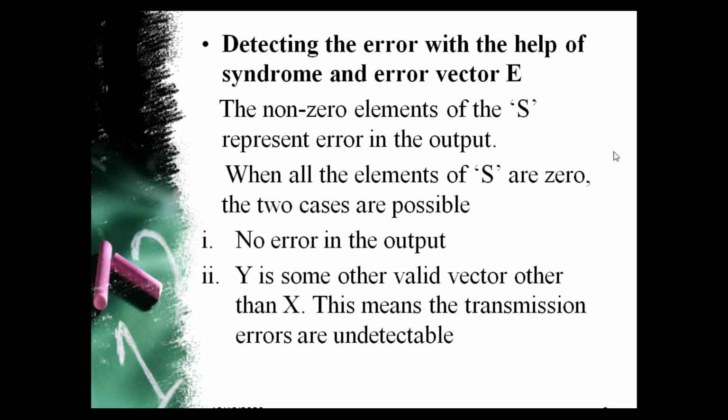Once it is given, we are able to generate or construct the linear block code. And once all the code words, all code vectors, are written, we are able to find the minimum distance, d minimum, of the code. From that parameter, d minimum, we can comment on the error detection and error correction capability of that particular code.